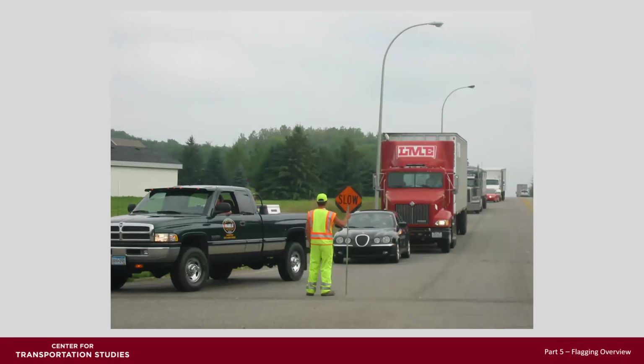It's hard to see on this slide, but this is actually an intersection with a turn lane with a lot of right turning vehicles. And that flagger is standing in the turn lane, trying to stop traffic. You should maybe be located in advance of the turn lane and controlling traffic before it gets to the intersection.